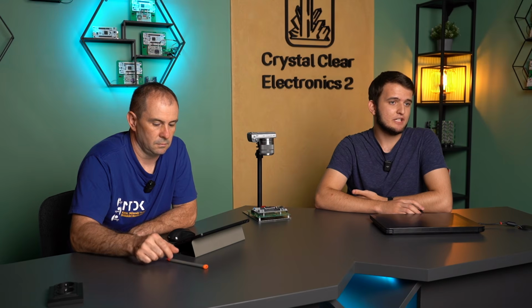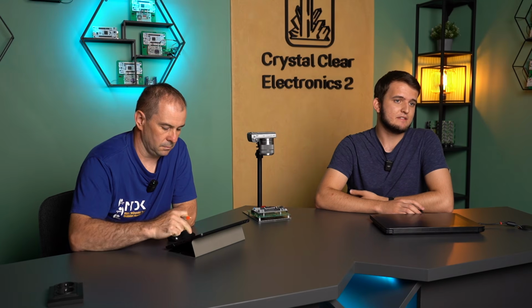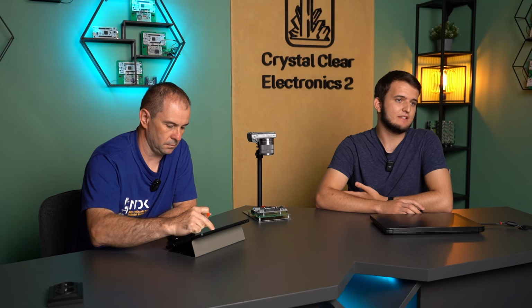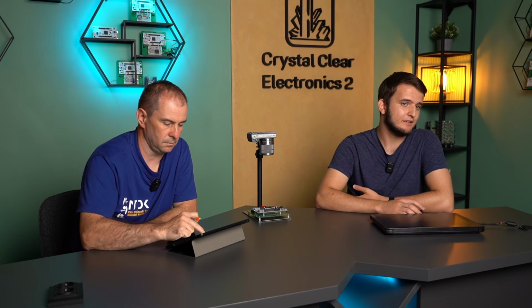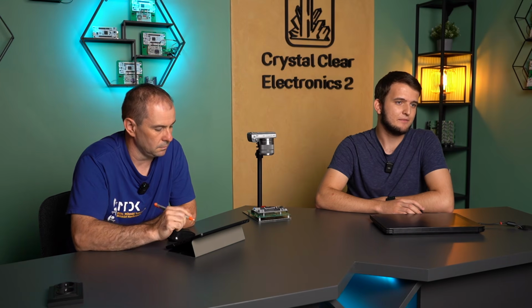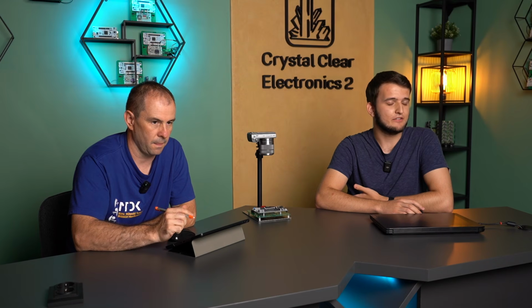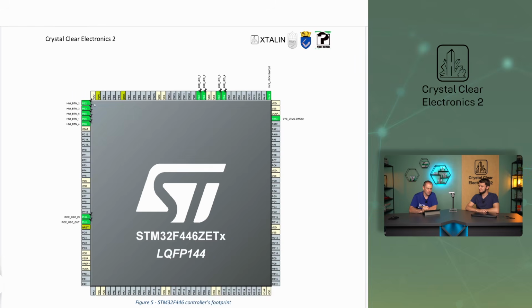In the following, I will describe the types of legs and their physical design using the STM32F446 microcontroller from ST Microelectronics. We'll also be using this device in later chapters. Our STM32F446 microcontroller is designed with LQFP144 packaging, which stands for Low Profile Quad Flat Package, where 144 represents the number of legs. There are 36 legs on each side of the device, which gives us 4 times 36, totaling 144 pins.